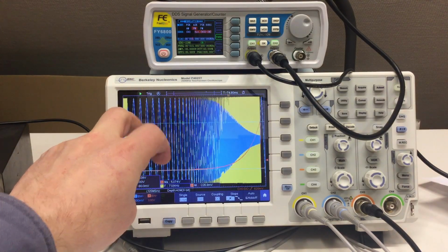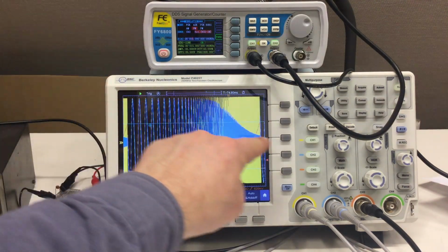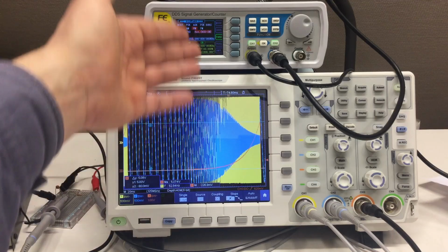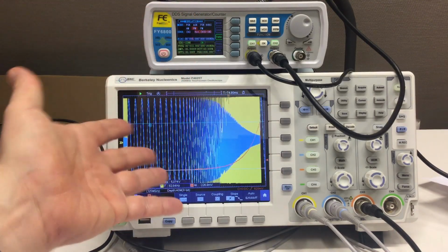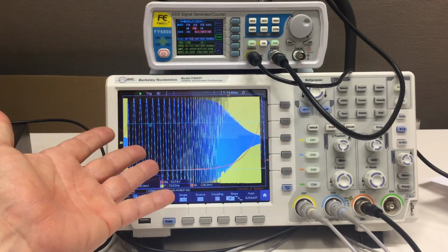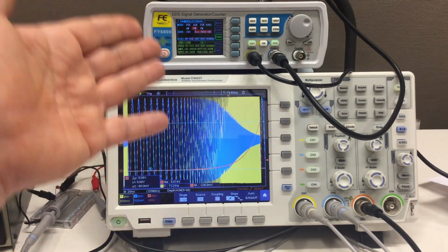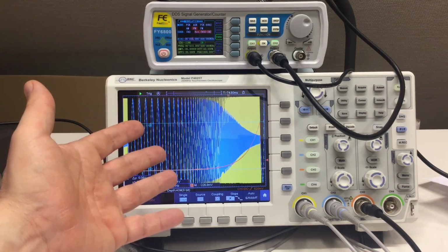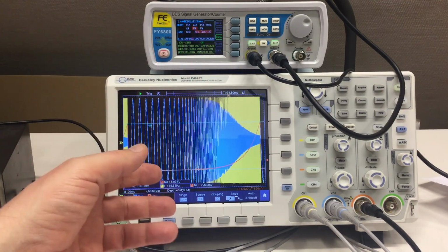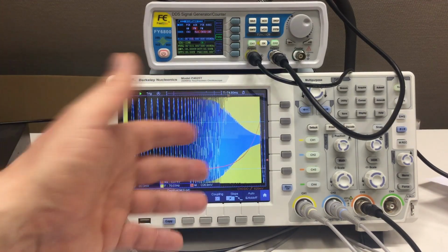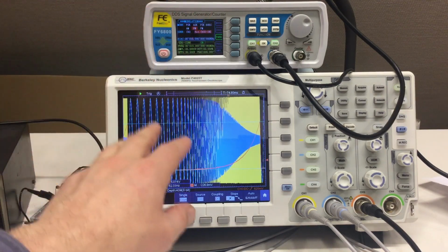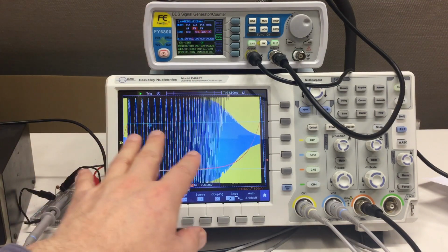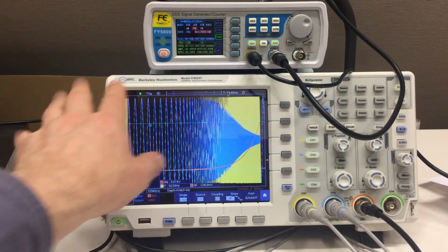So our poor man's Bode plot here is possible to do with frequency modulation, but I don't see any reason why you would do it. It's not as linear as the VCO, or whatever they tell on these boards, at least not for my unit and my firmware version. I'll give you a shot of the firmware version in a second.